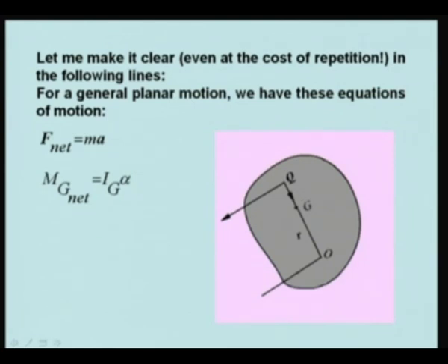So now this is in effect this point. If you take the moment about G, you will still get a moment, because the force is not passing through point G. So there is no need to show the force. Therefore this has been shifted, and this point Q will be called the center of percussion. Let me repeat these points because this is very important. So this point Q is the center of percussion we have described.